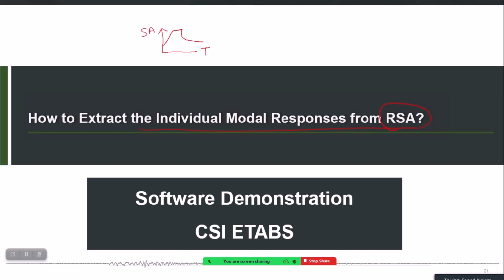If the purpose is to design a structure, this curve will come from a standard building code which you will be following for the purpose of structural design. If the purpose is to evaluate the response of a structure under a particular earthquake, this relationship should be the spectral acceleration versus time period for that particular earthquake. Obviously, for a real earthquake, it would not be that smooth, it will be an irregular shaped spectrum. So depending upon the purpose of your analysis, you will give this curve as an input, and then